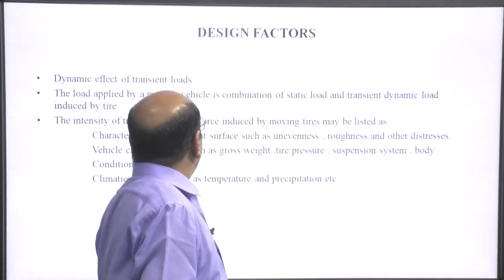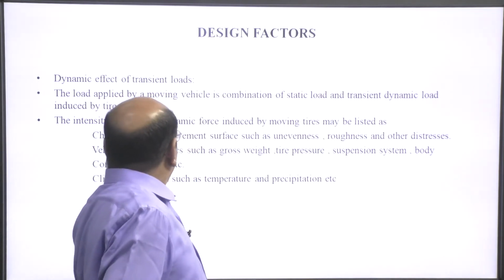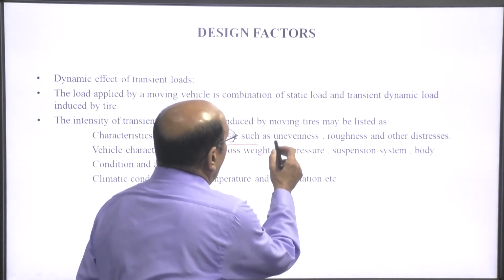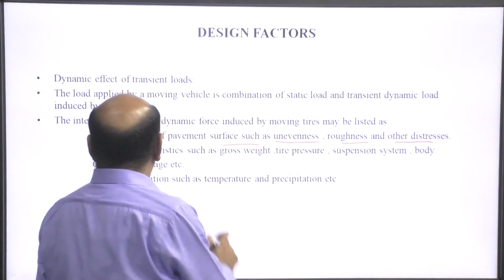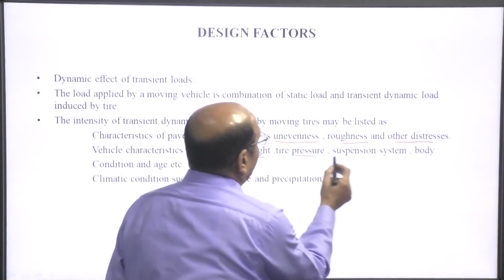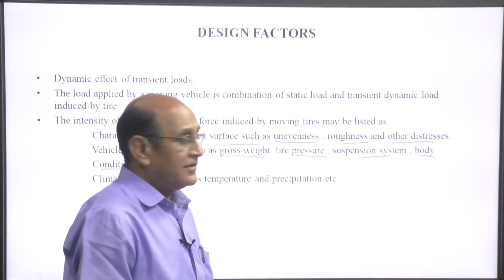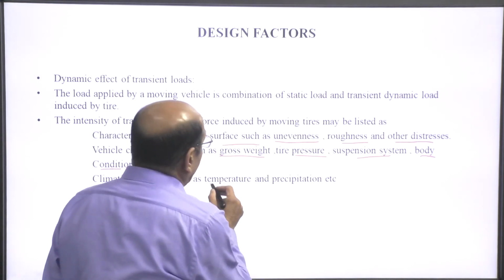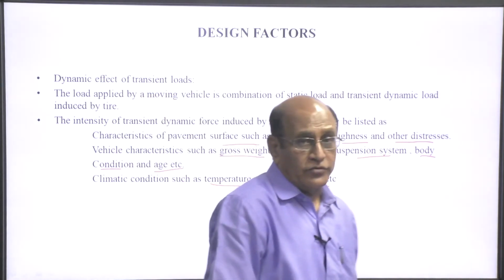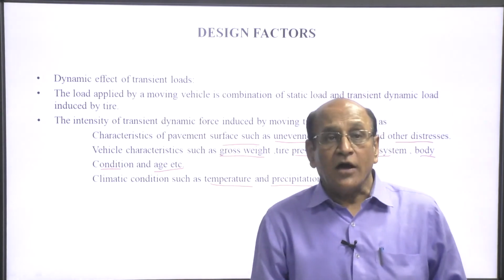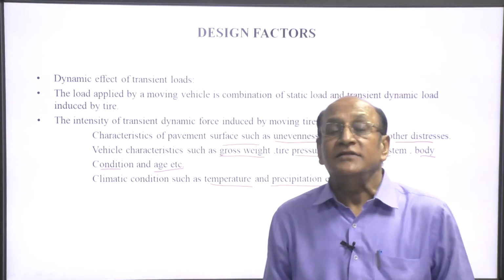The intensity of the transient dynamic force induced by the moving tire will depend on the characteristics of the pavement surface such as unevenness, roughness and other distresses; the vehicle characteristics such as gross weight, tire pressure, suspension system, body conditions and age of the vehicle; and the climatic conditions such as temperature and precipitation also affect the dynamic effect of transient load. Simple meaning of transient load is the combined effect induced by the static load and the moving load.